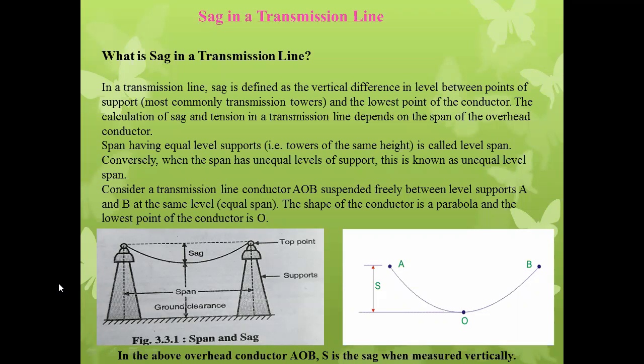So remember that the span of the transmission line, or the distance between the two supporting structures of the live conductors, is mainly affected by whether the line is crossing a river, railway, big obstacles like mountains or hills, road, canal, and turning of line. These are the main important points to be considered while deciding the span between the two supporting structures.